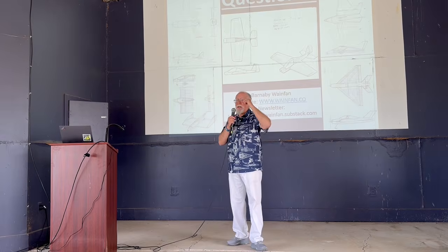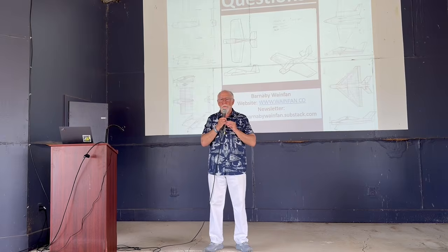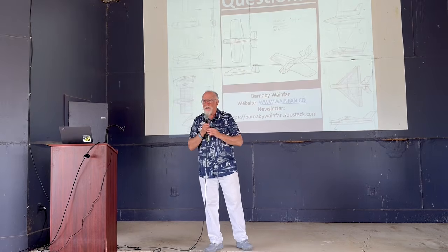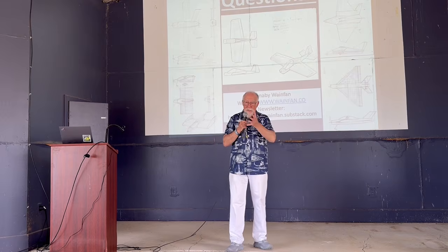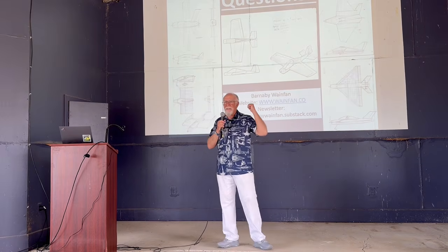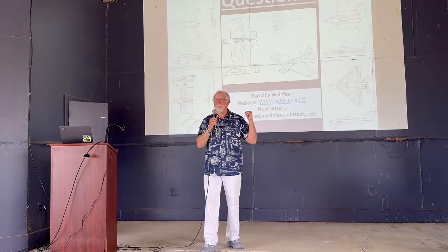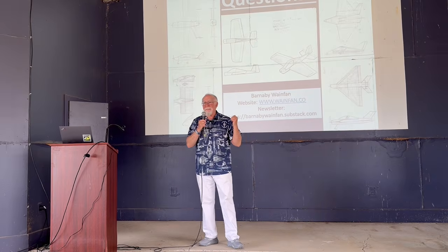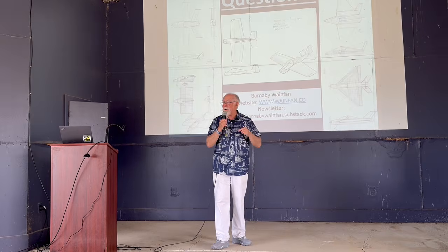I'm actually watching a kind of a sad story happen in my neighborhood, because there's someone who built a relatively well-known kit airplane, but has chosen to mount a non-standard engine, and it's just discovered that in order for it to balance, he needs 50 pounds of ballast in the tail cone. Not going to happen. And it's hard to tell him, you've got yourself in a corner, and none of us can help engineer our way out.